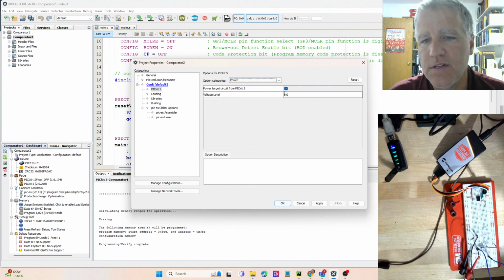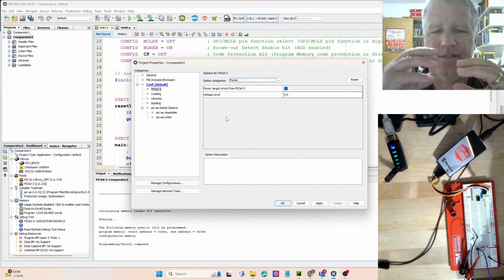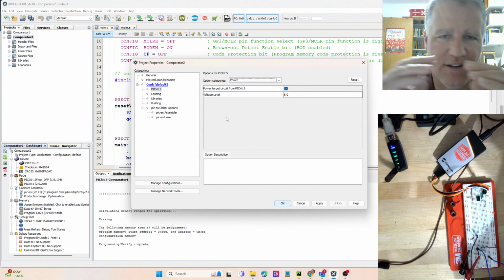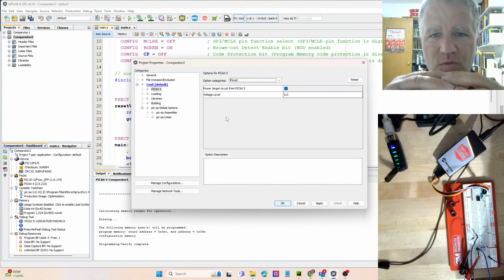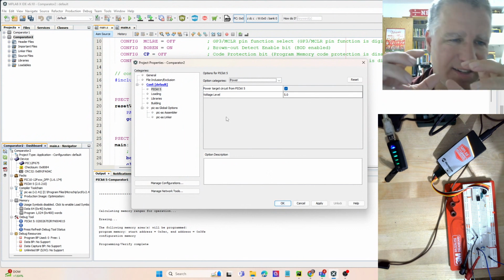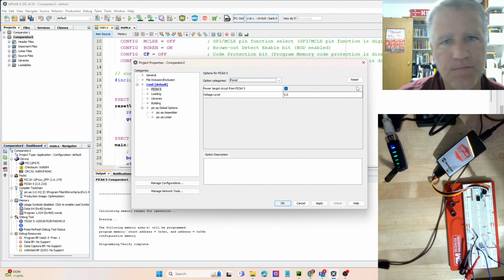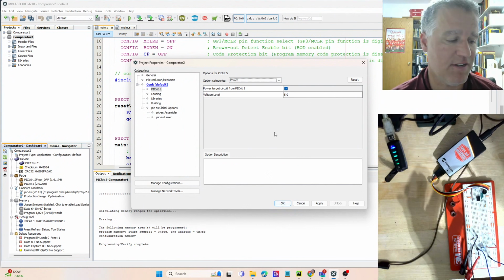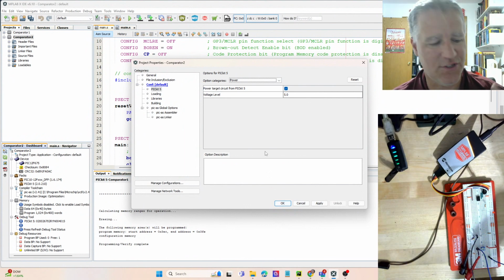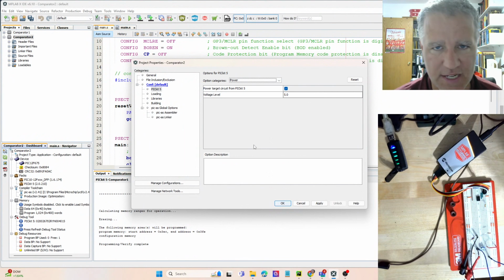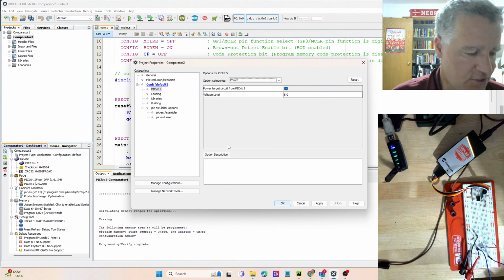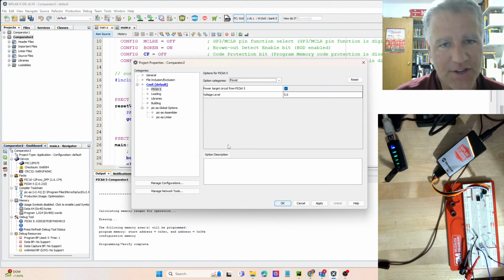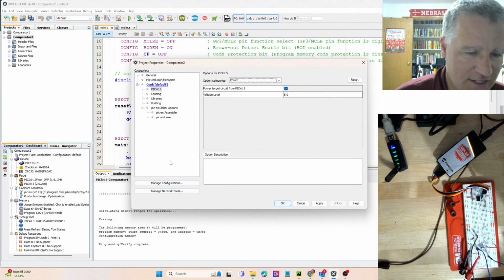Power. I've learned the hard way about having the power on while working with the pins as not GPIO. I don't quite understand exactly why, but I power this with the PICkit to do the coding. Then I'm going to take my PICkit off. I'm always a little worried about supplying voltages when the PICkit is on there. I'd hate to screw up the PICkit, and I certainly make a lot of mistakes in the wiring, so it could easily happen.